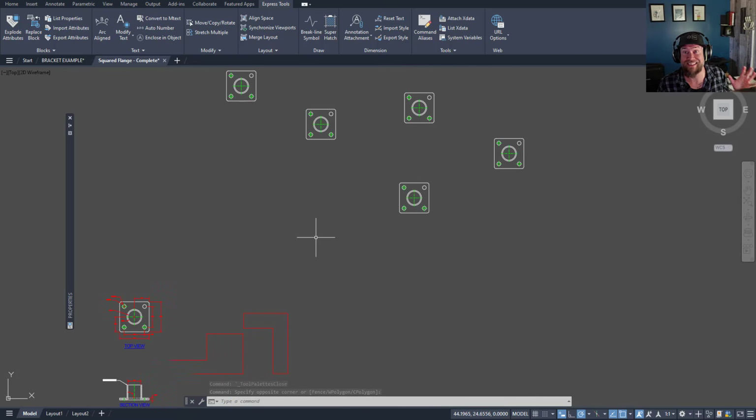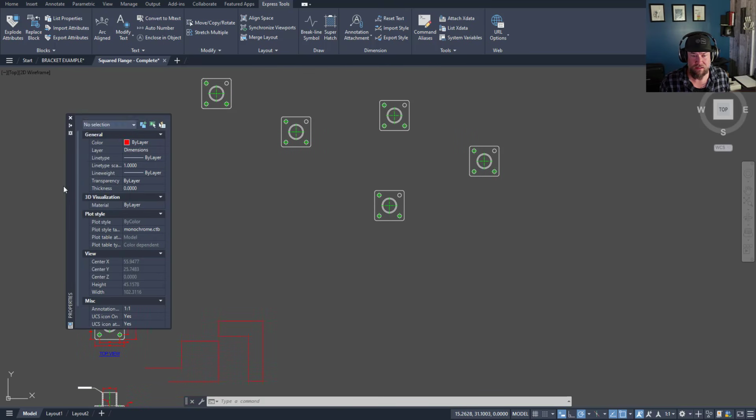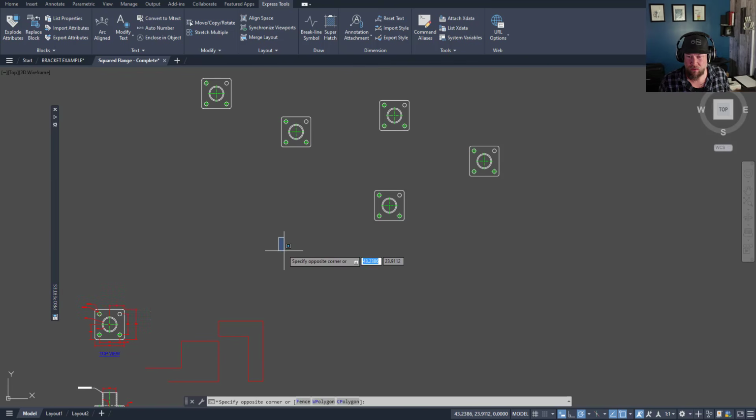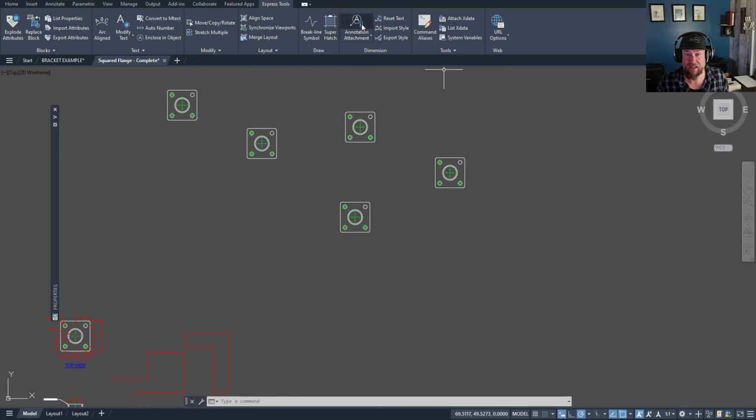Alright, so now we're on to the last tip, and this may be one of the best time savers within AutoCAD that I don't think many people actually use, and I don't understand why. It's one of my favorites, and it's one that I show people and it blows their mind every time. So tool palettes within AutoCAD are pretty common. All of these little windows here are kind of like a tool palette or a palette in general, but tool palettes in particular are a huge time saver because they take common commands or text objects or styles away from the hidden ribbon menus and place them front and center so that you can have all of the most used and common ones for your projects right next to you.